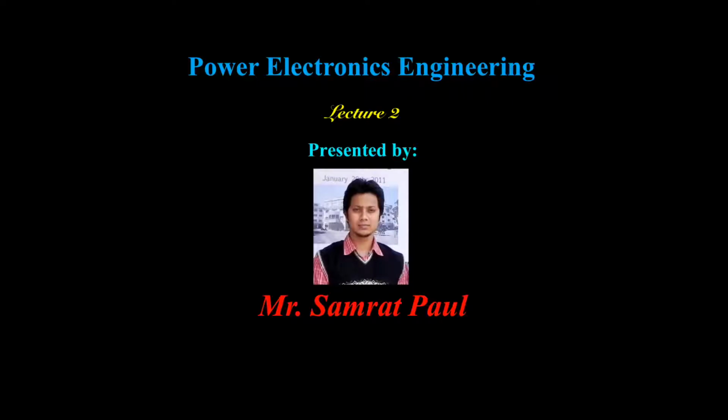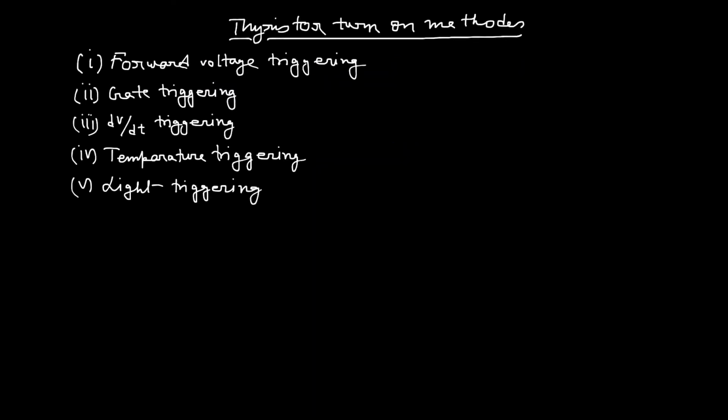Actually, there are 5 types of turn-on methods. Number 1, forward voltage triggering. Number 2, gate triggering. Number 3, dv/dt triggering. Number 4, temperature triggering and number 5, light triggering. The first is forward voltage triggering, and that is very easy to understand. Already we had discussed it in the previous session.